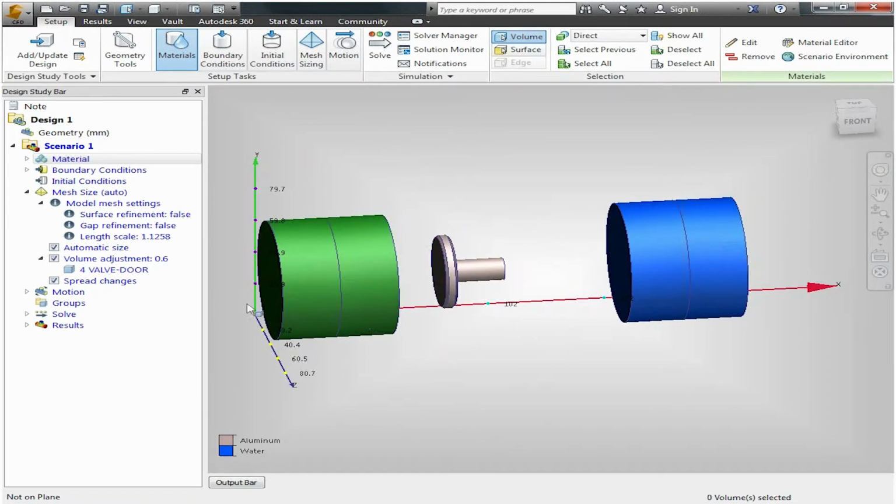So I added some intelligence so that the flow going from left to right will move this check valve when the flow reaches a nominal value. So this can help maybe if I want to determine the spring tension on the right end of the spring. So I already set up this whole thing and I've already run it.